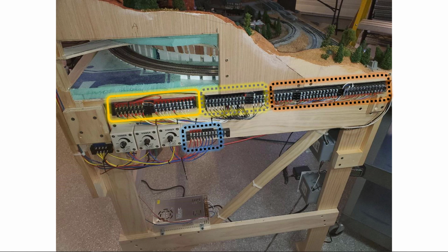Now, the blue highlight with black dots, that's the lighting bus. So I've got 3 dimmers, and I've got, remember the yellow wire coming from the LED lighting up above, that was from the common, which on the strips was white. So that comes back as a yellow, and it goes to the minus side of the output of each of those dimmers.